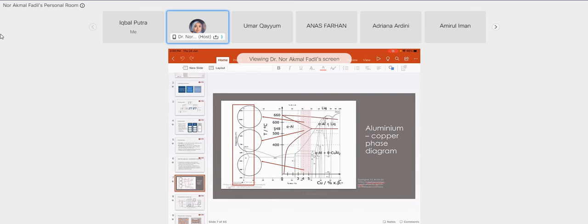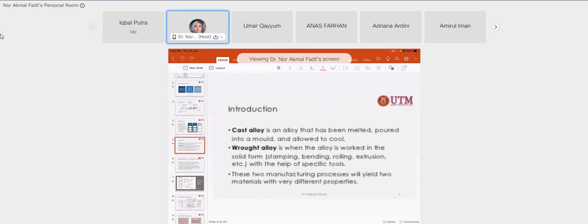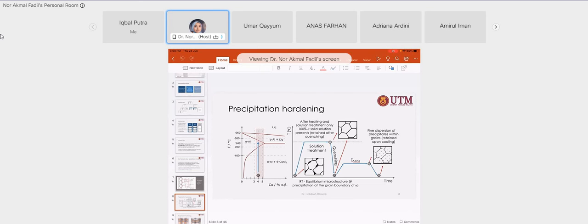Okay. So aluminum is one of the structures that applies this. Heat treatment of alloys. Okay. Precipitation hardening. If we do heat treatment on alloys, unlike steel, where there are various heat treatment processes dedicated to steel, for the non-ferrous alloys we have a heat treatment where the purpose is basically to have precipitates. We want to design the precipitates. So in precipitation hardening, this is more detailed.